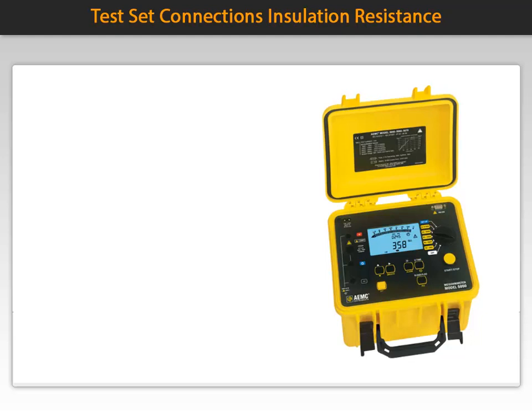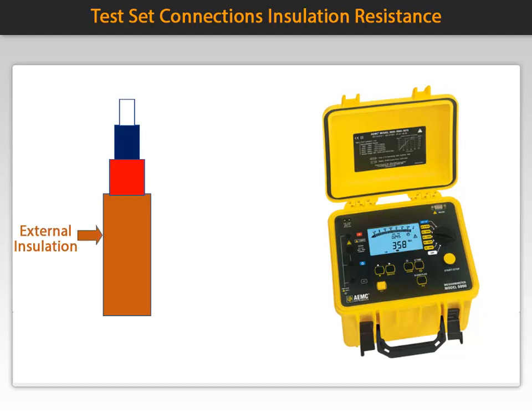Next up, we'll touch on how to make connections to the test set for insulation resistance testing. First, let's review the specimen. In this case, it's an electrical cable. It is made up of an external casing or insulation. Next, you see the shield or braid. Next is an internal layer of insulation. Then finally, the conductor itself.